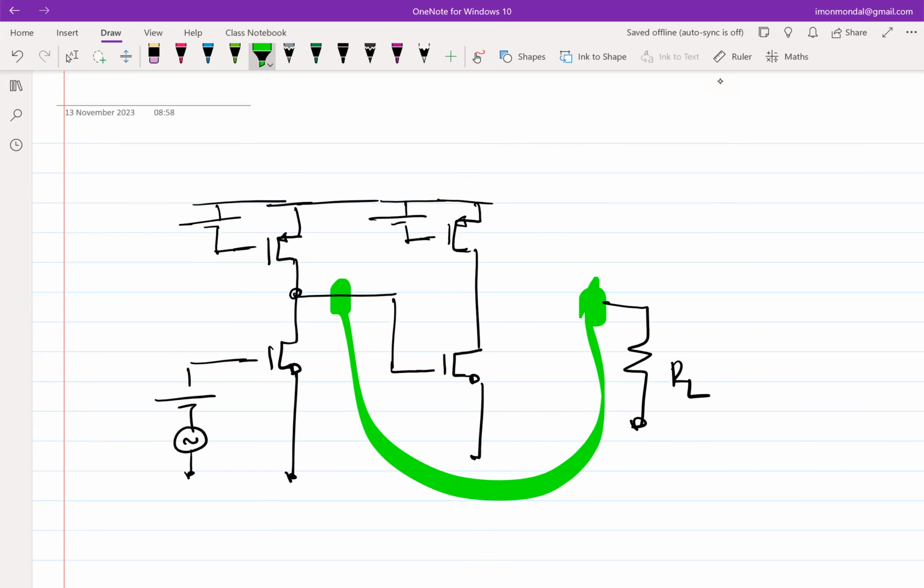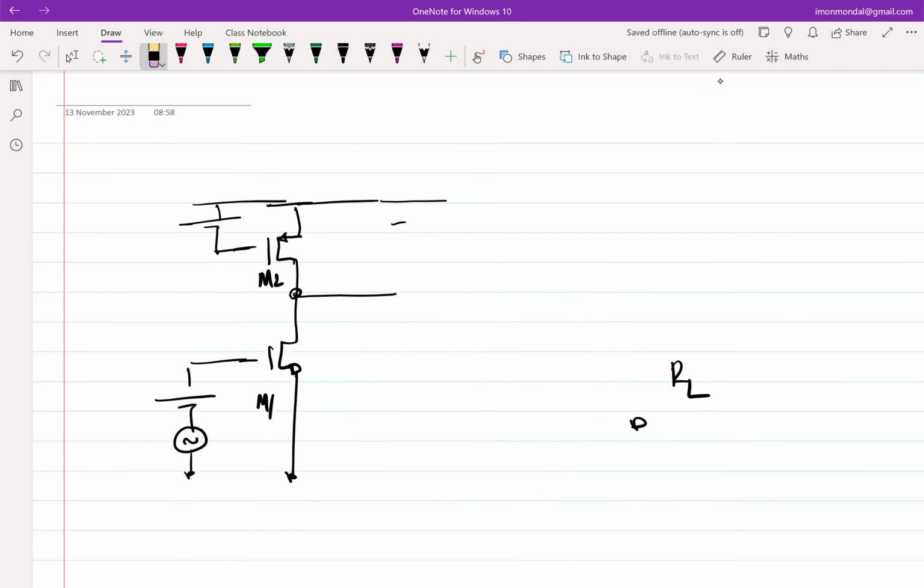What will be the first stage gain? GM times? Right, so there are two transistors, let's call them M1, M2. So let me get rid of the second stage because we're not talking about it anymore. So the gain, at least the DC, low frequency gain, is minus GM1 by (GDS1 plus GDS2), right? So this is the gain.